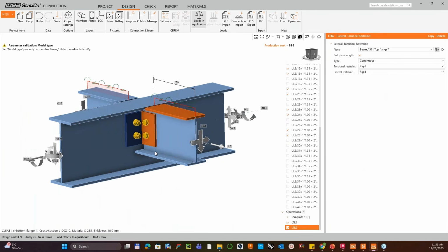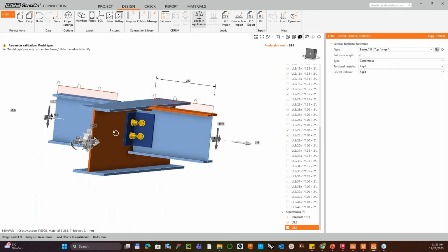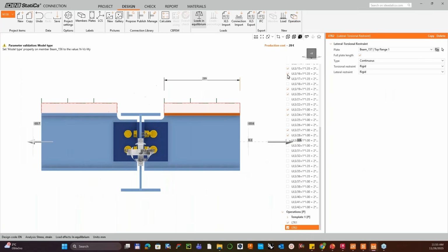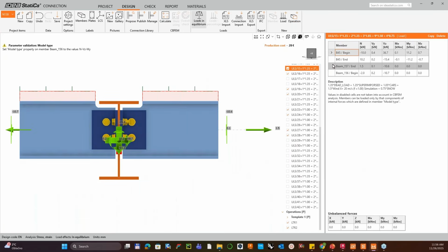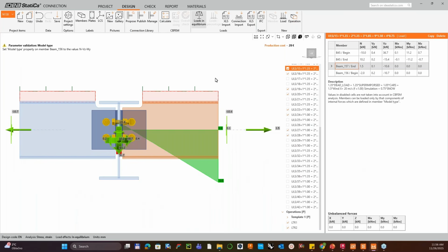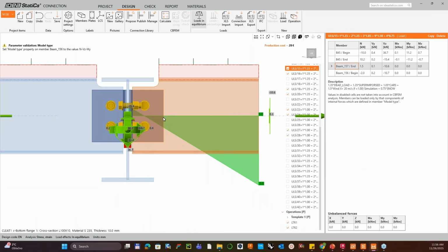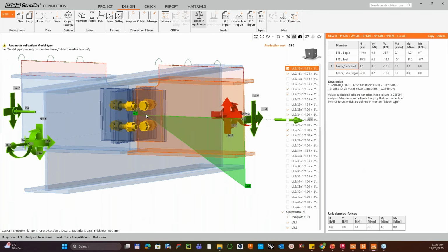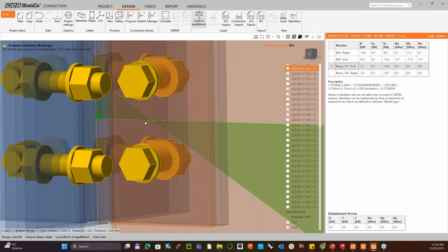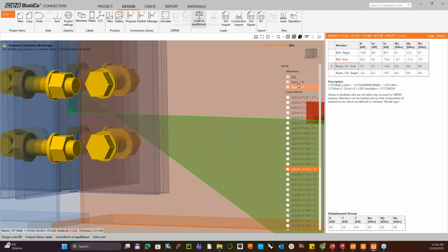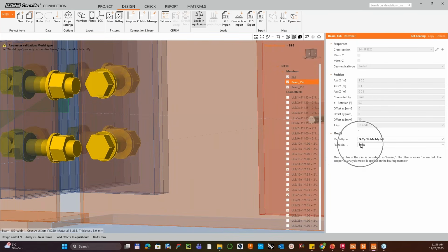Yeah. So what you don't need to omit is the internal forces. If you double check, and you will check the beam, and the trend of the internal forces, I mean the bending moment, you need to assign that the shear force is coming through the bolts. This is not a general rule, but for this type of connection, which is really a shear connection, the shear force will be passing through the bolts. How to do that? If you just go to the beam and assign that the forces are coming through the bolts, you will get the proper shape of the bending moment. That's very essential. What will happen if you neglect it?